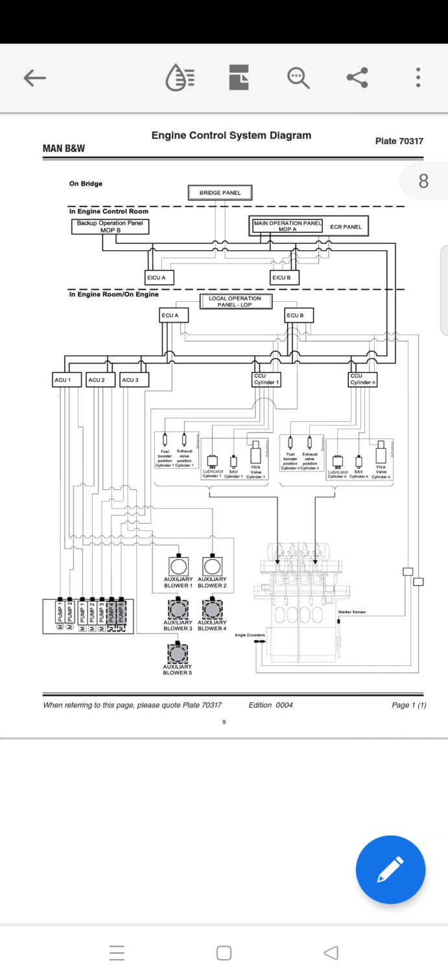Now, what is MOP? The main operating panel is the main information interface for the engineer operating the engine. The MOP communicates with the controllers of the ECS over the control network. However, the running of the engine is not dependent on the MOP, as the commands from the local control stations are communicated directly to the EICUs or ECS.